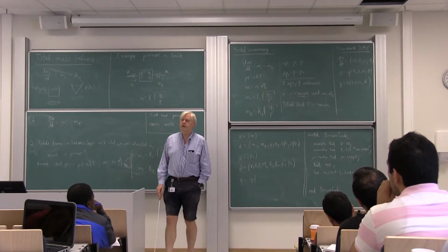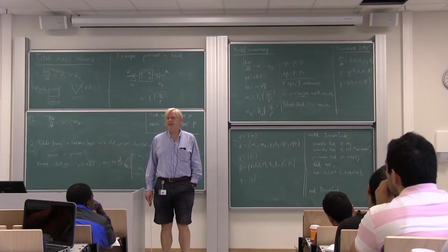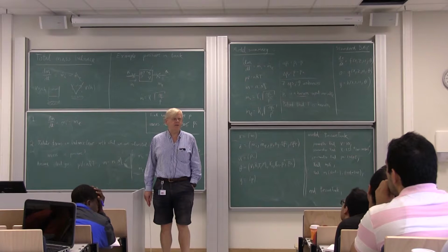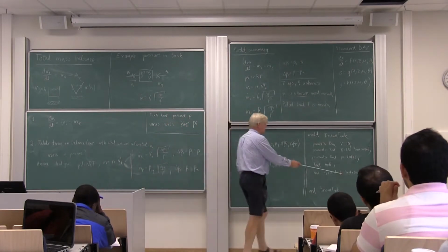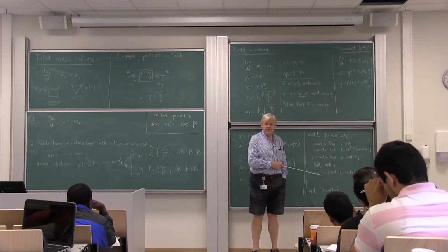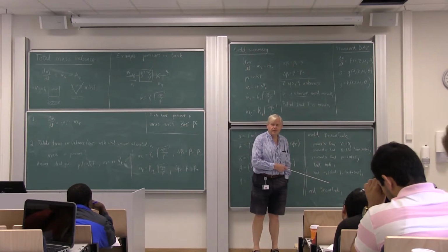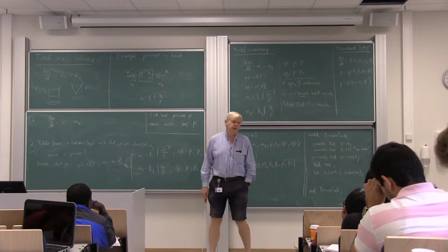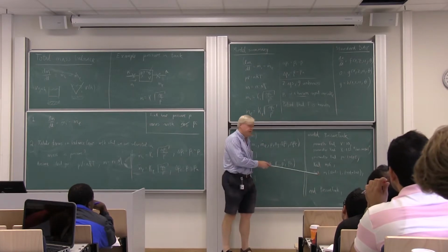But then the solver has a problem because you have specified too many initial values, and then it has to figure out which one is the right one, or maybe take some least squares choice. If you say that fixed equal true, then it has to use this value. And if you use fixed equal true for several variables, the system will crash. So fixed equal true is a way to say which one it has to start with as the initial value.